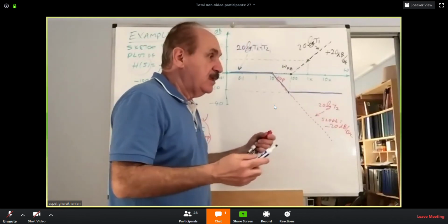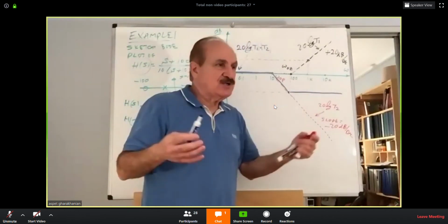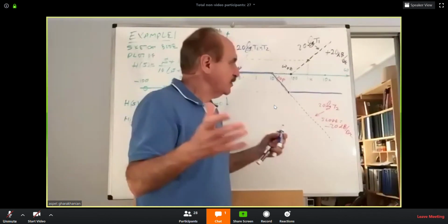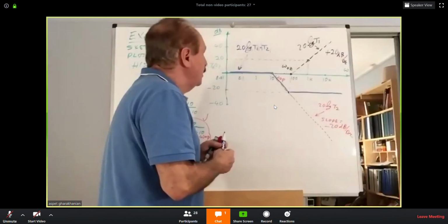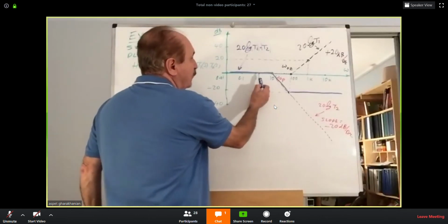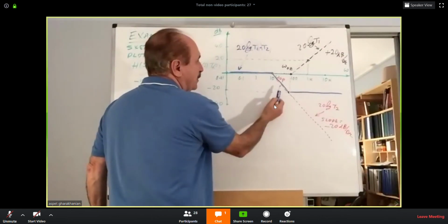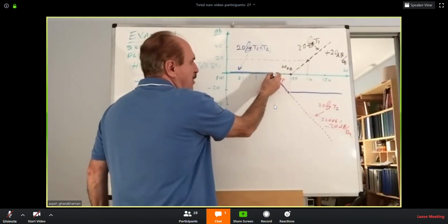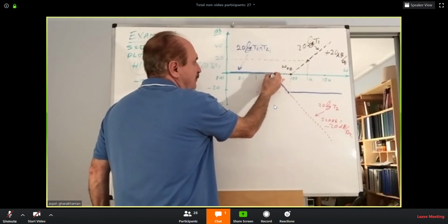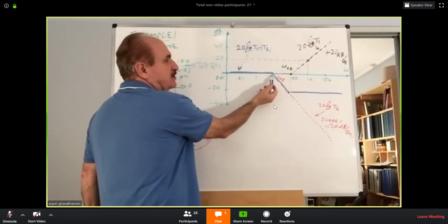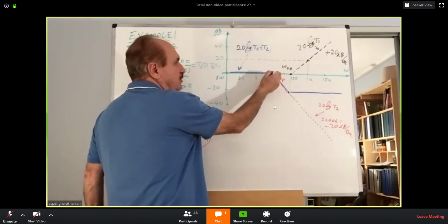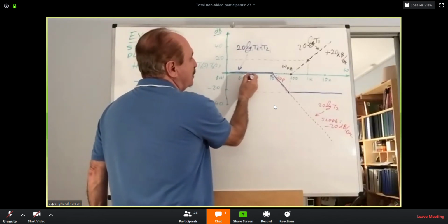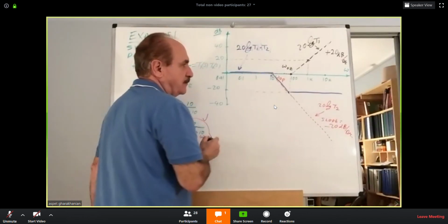Now, if it comes to the correction and you wish to refine it, what would you do? Refinement. Please note, for the poles, the red one, there was only a 3 dB down. So if you walk 3 dB under the 0 to -3 dB, mark this point. We know that the actual curve goes asymptotic to that, then passes through here.